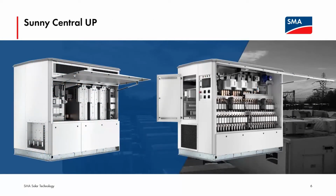For those of you who have never seen a central inverter up close, here are some open doors impressions of the PV inverter variant. The right-hand picture shows the DC compartment with the PV input fuses and 3 DC contactors. The open compartment to the left of the operator's panel hosts many of the printed circuit boards for the control of the inverter. Underneath is the cooling air outlet. The left-hand picture shows the AC compartment. In the middle are 3 power electronic stacks operating in parallel. AC filter and circuit breaker are hidden behind the doors at the bottom.